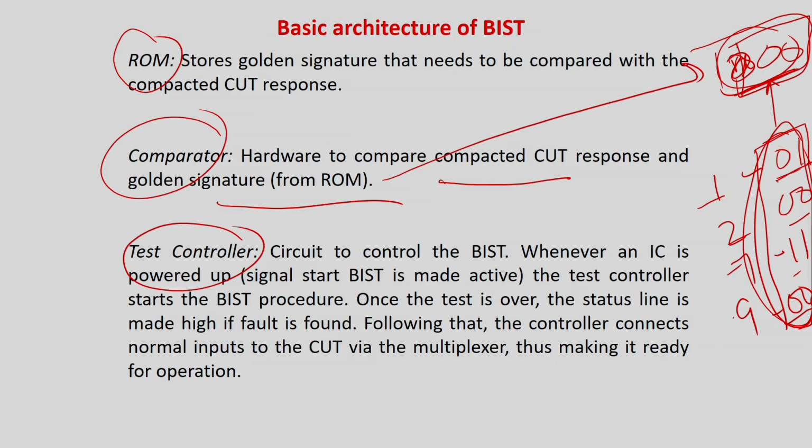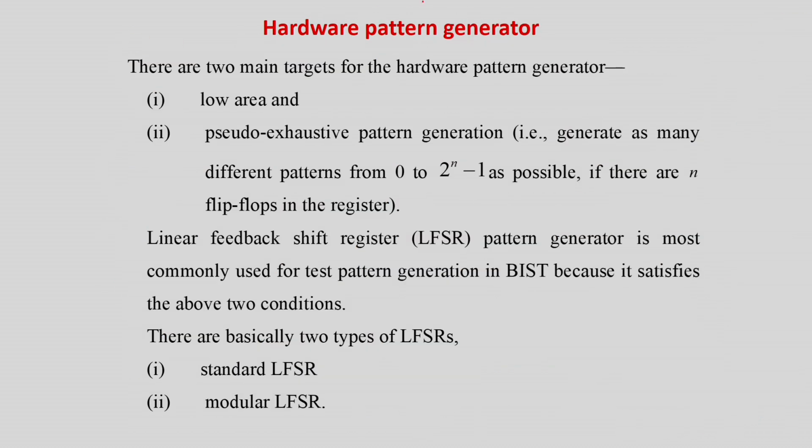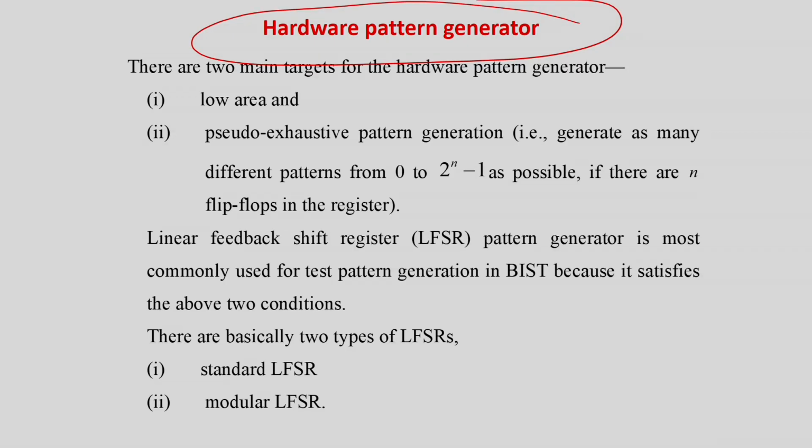Now we are going to look in detail at the hardware test pattern generator: how it has to be designed, how it has to be tested, basically how it is such a miniature version. Even so, it generates a large sample space of patterns for an n-bit input bus. The only thing that cannot be generated is all zeros.